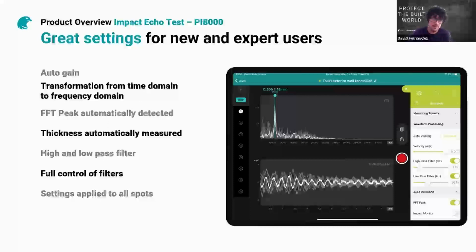Then we have a lot of additional settings that are really good not only for expert users, but also for new, non-expert users. So we have this auto gain functionality. We automatically do this transformation from time domain to frequency domain. Of course, as I said, the frequency domain is easier to understand than the time domain graphic. Also, this peak on the frequency domain graphic is automatically detected. So then you will automatically have the thickness of the element.